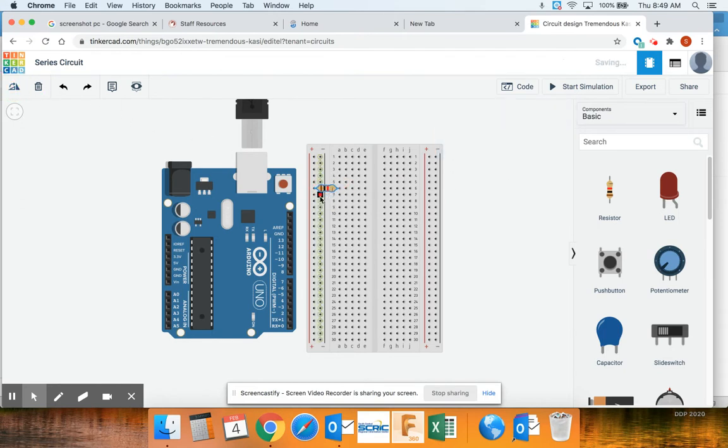First thing I'm going to do is bring a resistor in, rotate it, and bring the resistor to my positive lead and jump it over to one of the terminals over here. With my mouse, I can then grab 5 volts DC, bring it into my positive lead, and I'll make this red. Keep in mind the positive lead is all interconnected vertically, as is the negative. All of these items are connected horizontally, as you can see with my mouse. So keep that in mind when you're trying to have your electrical flow through the circuit correctly.